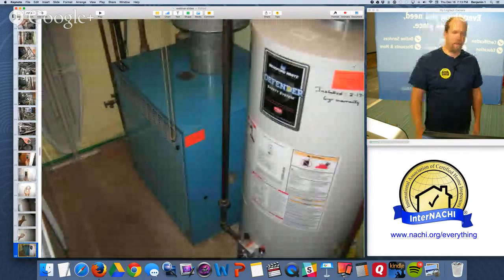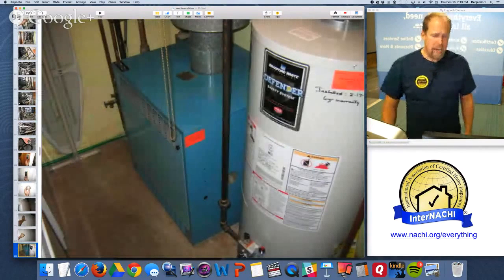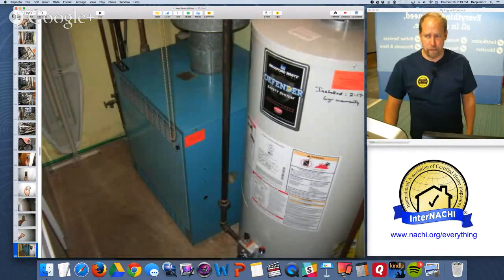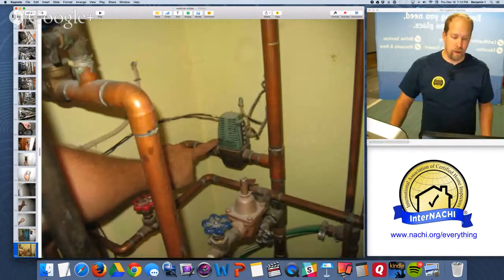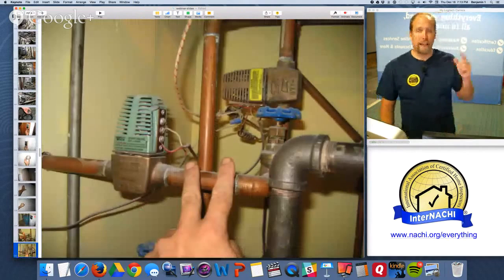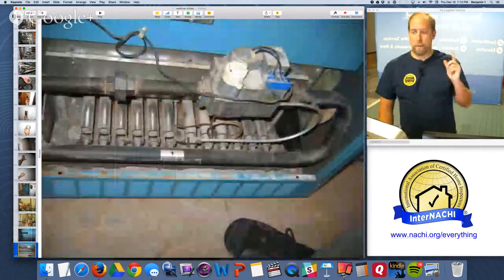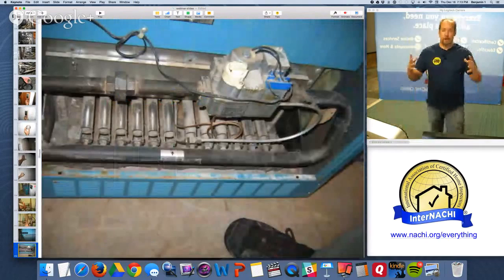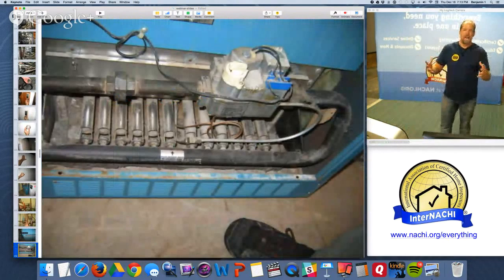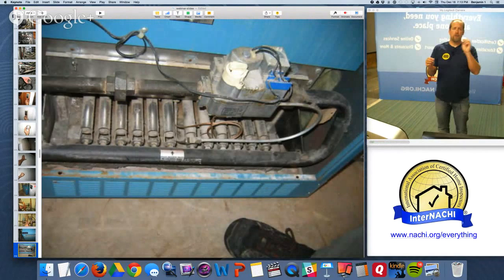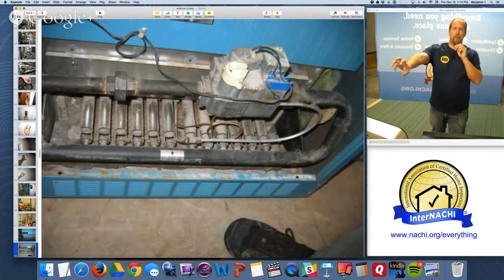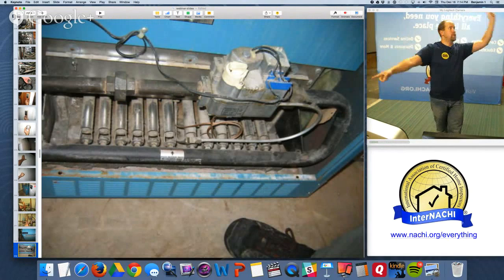There's a boiler system right next to a hot water source, gas-fired boiler, gas-fired hot water tank, natural draft at the boiler, natural draft at the hot water tank. The components of a boiler system are a bit complex. There are valves controlled by thermostats that allow the water to flow because there's a pump. A boiler is a big container, typically cast iron, filled with water, flames underneath, heats up the water. A pump turns on at a certain temperature and circulates the water throughout the house. Multi-zones could be controlled by thermostats, and there's valves and different pipe distribution zones.